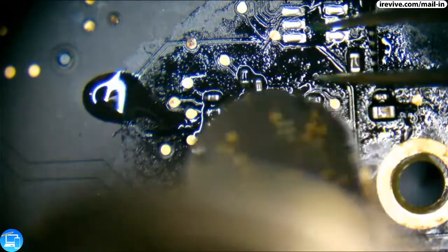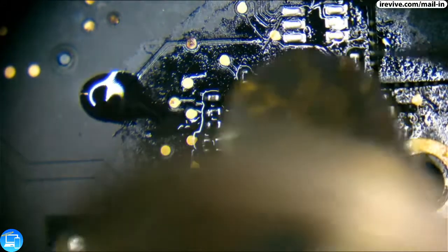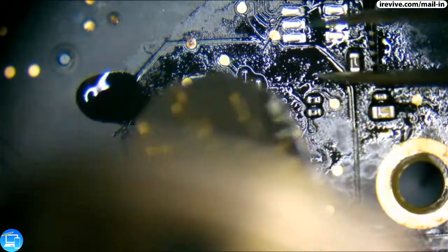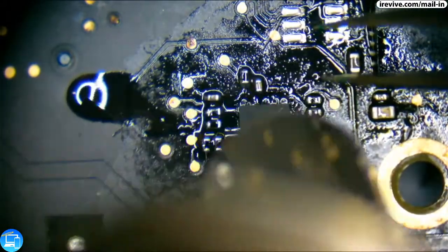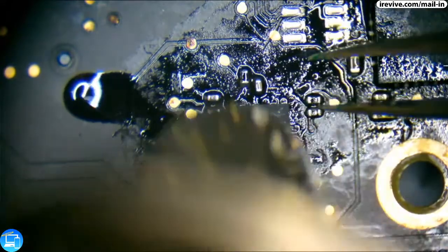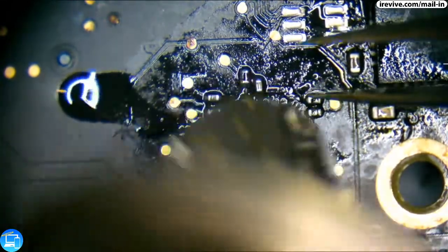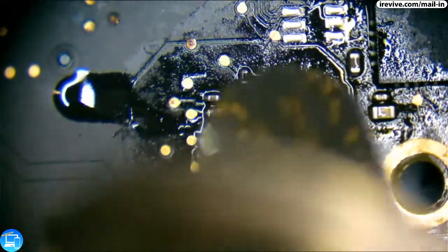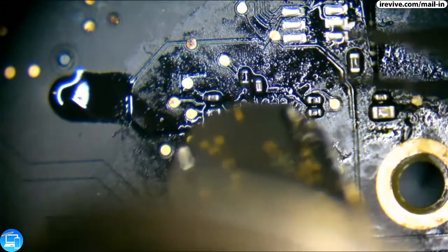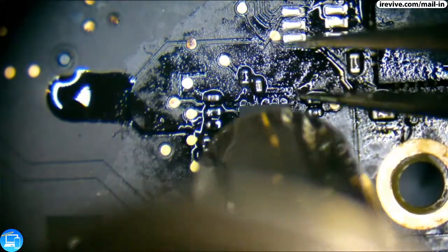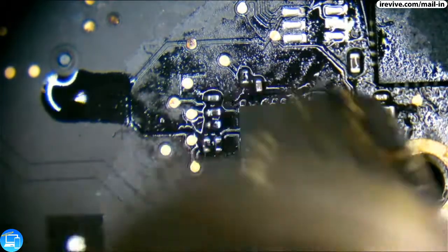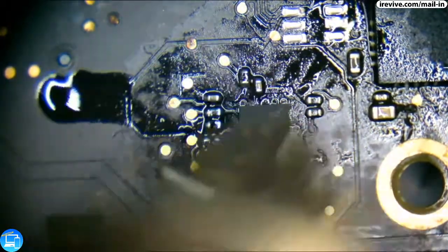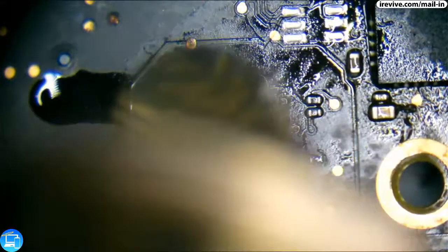So, if you use the Quick 861DW, I have mine set to 50 or 60 when doing BGA rework. But whenever I'm in the process of just moving the BGA off, I use more around 80 to 90 for the output. It does take a little bit longer, but it is going to prevent the chip from blowing away.